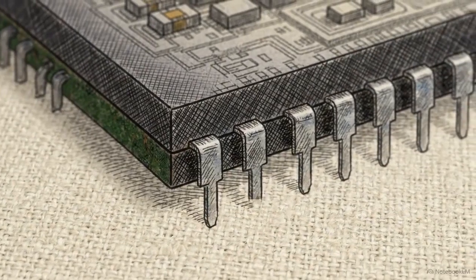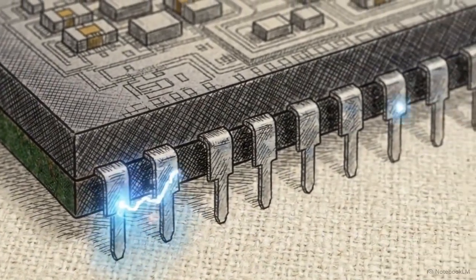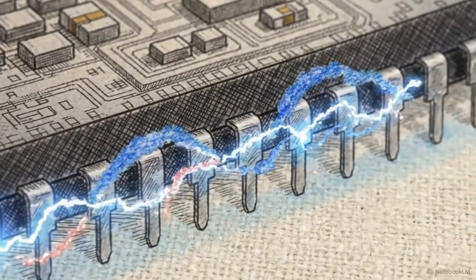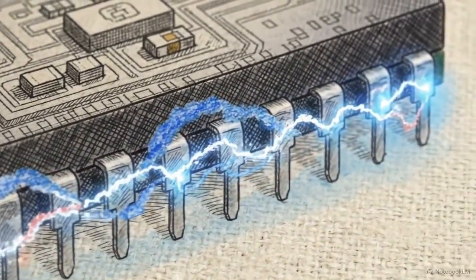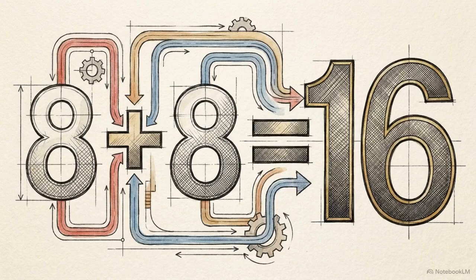At the same moment, the controller outputs the lower byte of the address directly onto its dedicated A0 through A7 pins. By multiplexing its data lines and using an external latch, the 8237 establishes a 16-bit address, proving logical timing can overcome physical pin counts.